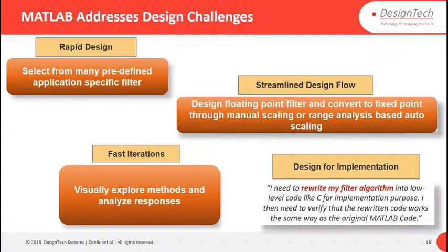Streamline designing. In MATLAB we have Fixed-Point Designer. Why do we need to convert our signal properties and parameters to fixed-point type? Because if you have to deploy on an FPGA board, we require converting from floating point to fixed point. These things are automatic. You don't have to write code; if you want, you can, but you may not need to.